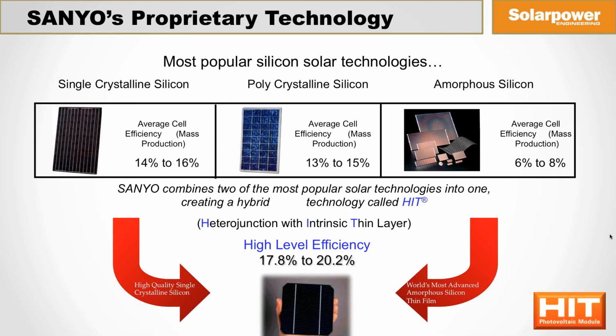And we all know in the crystalline world, the weather is perfect when it's cool outside, when it's sunny but cool, which isn't every day. In fact, most days are not perfect. Most days they either don't have enough sunlight, or like we're talking about high temperature environment, that's too much sunlight. So that's a time when finding the right technology that has this lowest temperature coefficient is the choice for building more kilowatt hours.